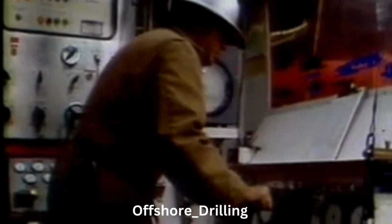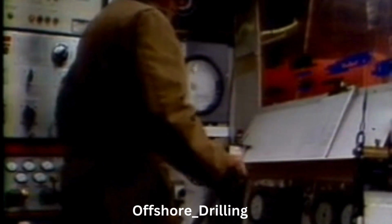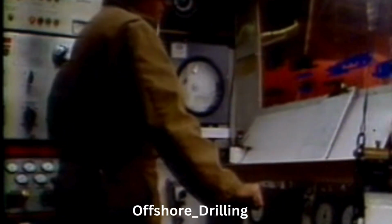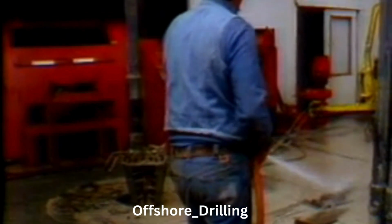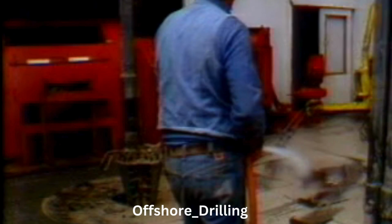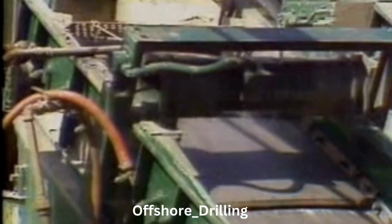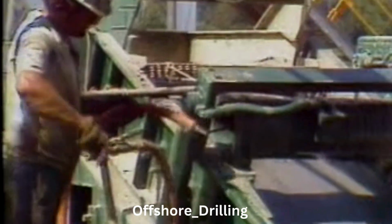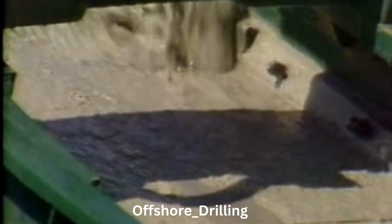Or maybe your driller has drilled into a formation that's adding fine particles to the mud that can't be removed by the solids control equipment. Or it could be something as simple as the drill floor crew washing down the pipe and the floor with too much water and diluting the mud. Another common problem is somebody washing down the shaker screens, like this. This can add too much water to the system.